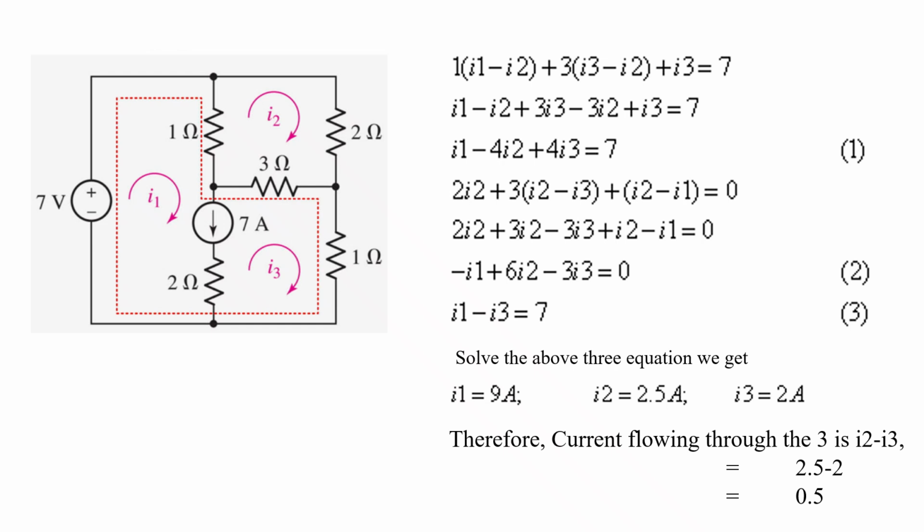Now we'll go to the second equation, that is loop 2. As I already mentioned, there are 3 loops, but we are just virtually eliminating the current source branch. So we have only one loop, that is, loops 1 and 3 will be merged and become a single loop. So now it is actually only a 2 loop circuit. So the first loop is over. Now we are going to find the second loop current.